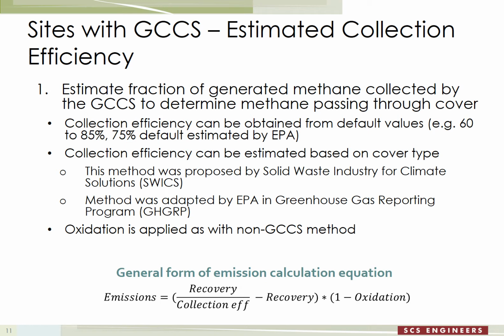The landfill industry, via the Solid Waste Industry for Climate Solutions group, actually developed a methodology for estimating the collection efficiency of a landfill based on different cover types and other parameters. That methodology was actually adapted into the US EPA Greenhouse Gas Reporting Program. And as with all of the methods, methane oxidation is of course applied at the end to any residual gas that's not being collected.